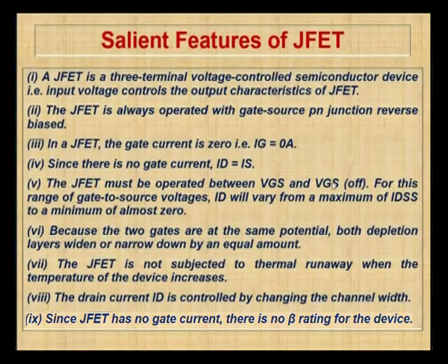A JFET must be operated between VGS and VGS(off), that is, between the gate to source voltage and the gate to source cutoff voltage. For this range of gate to source voltage, ID will vary from a maximum of IDSS to a minimum of almost 0.